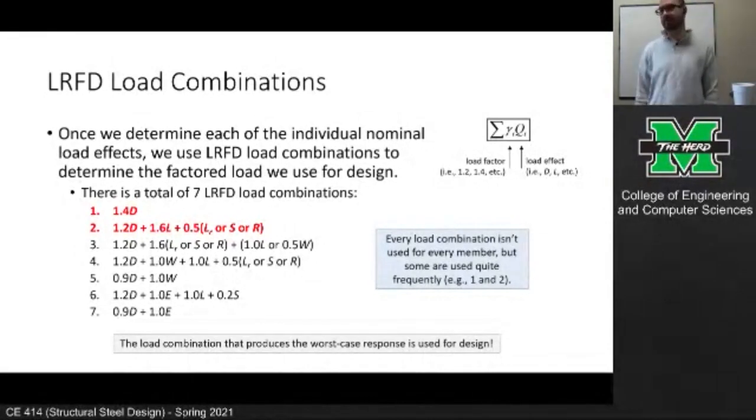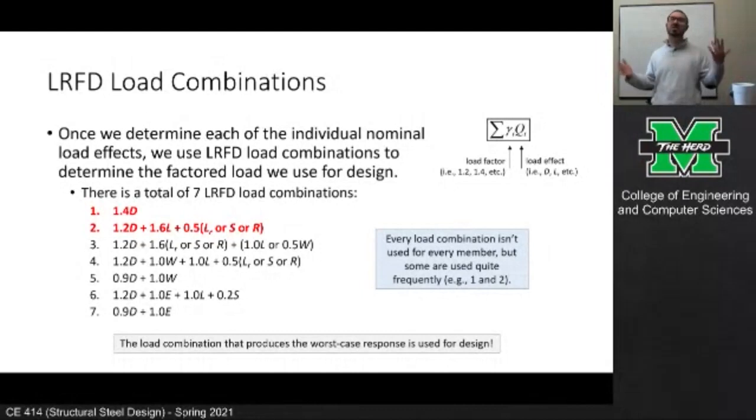During construction. During construction, there's no occupancy load in the building. Now, in fairness, in real world instances, we do tend to apply a construction live load for the workers when they're casting the deck or what have you. But in those instances, you can find that the dead load effects far exceed the live load effects because there aren't any live loads, because it's being built.